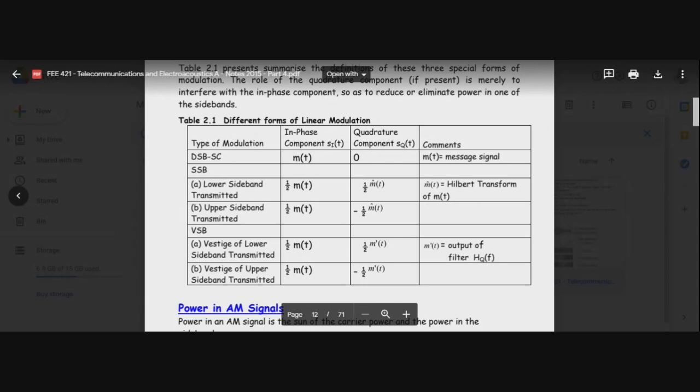We are not going to use it, but we point out the Hilbert transform basically has got a characteristic in the frequency domain, which is a brick wall. The filter that I was describing, which is difficult to design, is basically just that. It's zero on one side, and it is up on the other side, like a step in the frequency domain. And even though in mathematics we can write a Hilbert transform, in practice it's impossible to build it. You can approximate it, and so on.